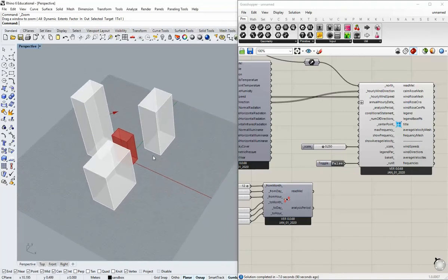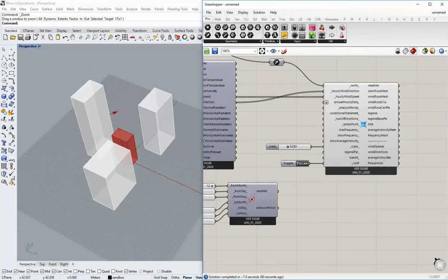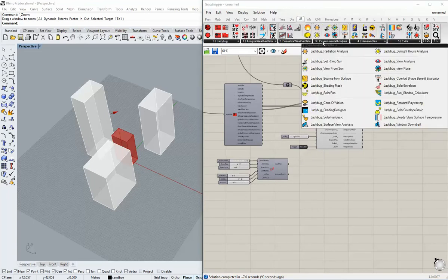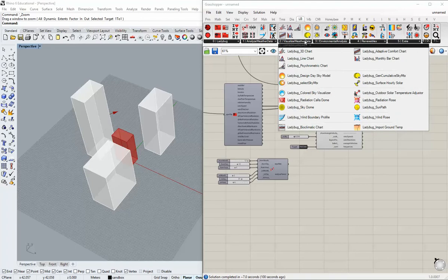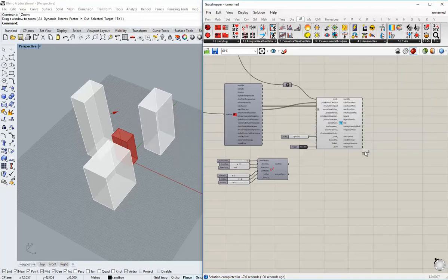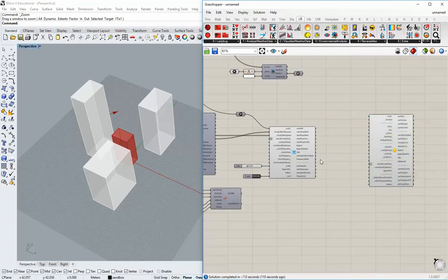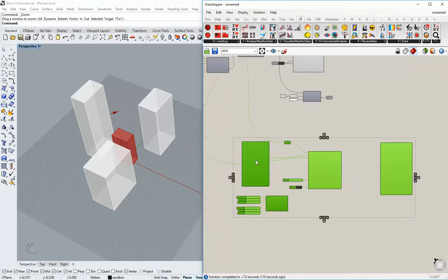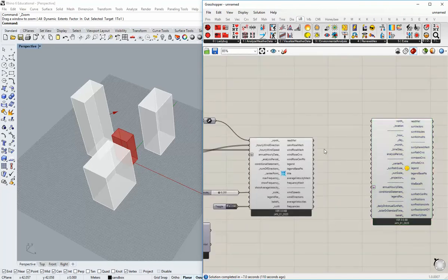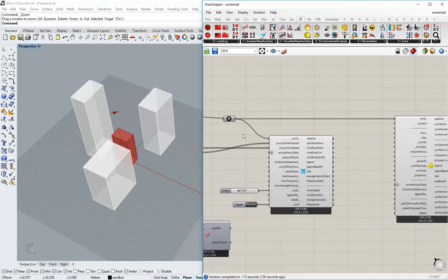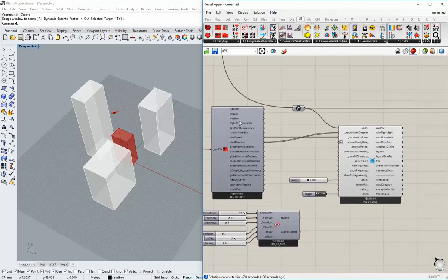This is also something that I think you've been asked to start analyzing on the site. So let's go to Ladybug and let's see if we can find it. Yeah, visualize weather data, Ladybug Sun Path. All right, and we've got just about all the information we need over here. I'm going to put it next to the wind rose. Kind of keep these things organized. North we're going to need, and we have that vector right there, nice and conveniently. Location also comes directly out of this import.